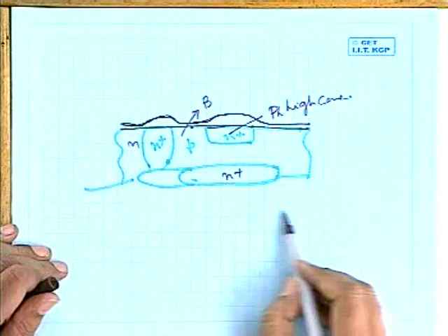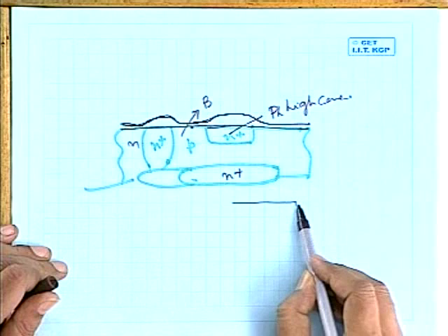So then in the buried layer portion, the oxide thickness will be more compared to the other regions. Since the oxide thickness is more there, it will consume much more silicon compared to the other places. As a result, if you remove the oxide later on, then in the buried layer region you will get a very small groove, just like this.